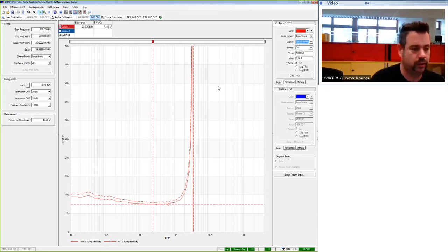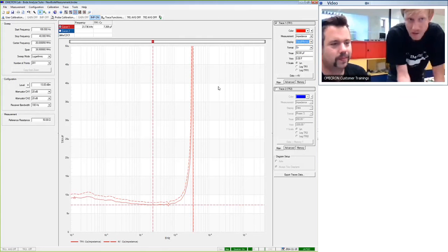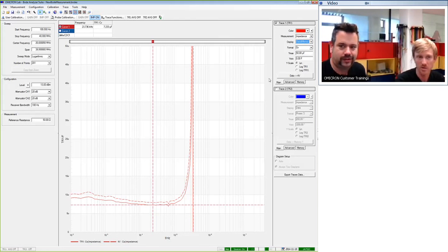And in addition, Bernhard, what we see here is the aging of the capacitor, because I soldered it just a second before. If you solder ceramic capacitors, you will de-age them, and then you are in the fastest aging process in the beginning. We are in the first second now. So what we see here is also the aging of the ceramic capacitor. This is something we recognize when we have done this measurement: the ceramic ones, if you solder them, you de-age them immediately.